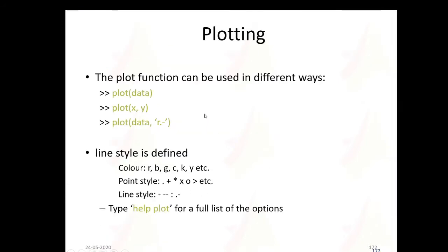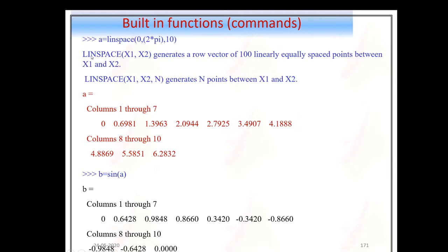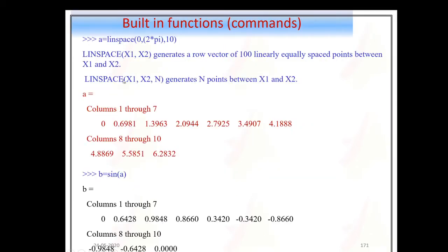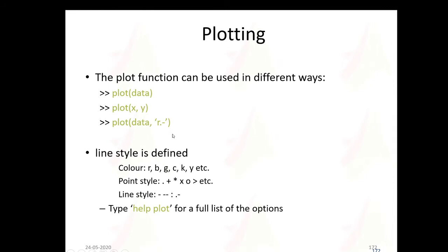I hope that you understand the speciality of the linspace command. Now let us go to some plotting functions. The plot function is used in different ways. Plot of data: if I give only the 10 data values, it is plotted by the samples. For the 0th sample, what is the data? The data are considered for the y-axis. This is for the zeroth value, what is the data, first value, what is the data.